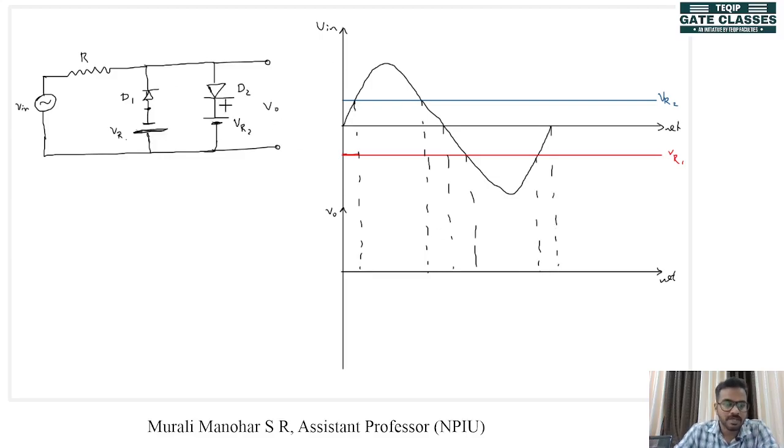so when we look at the circuit during the positive half cycle, we'll look at D2, because during the positive half cycle D1 cannot be turned on because the anode of D1 is connected to a negative voltage. Cathode voltage is never going to be less than the anode voltage during positive half cycle. So during positive half cycle, we don't have to bother about diode D1.